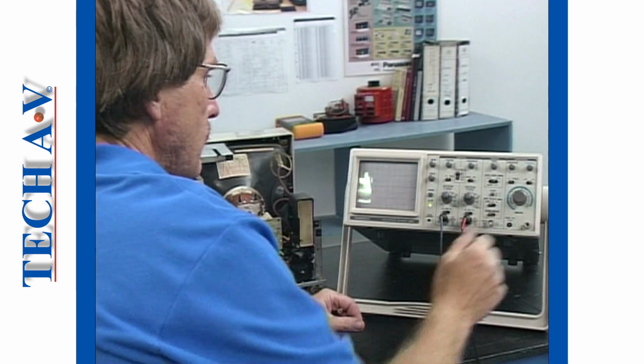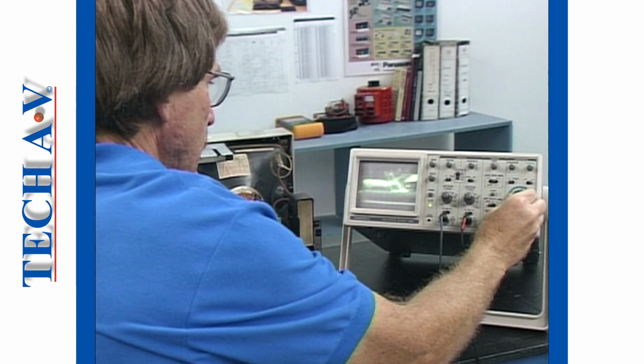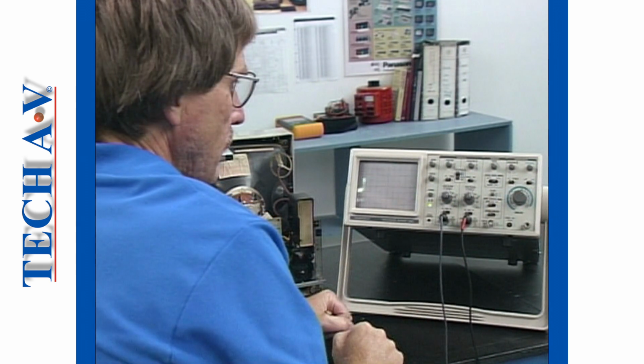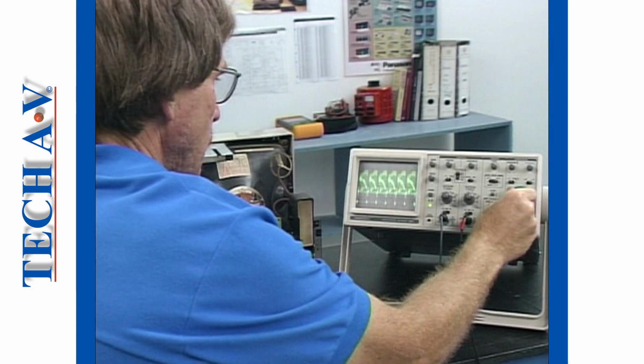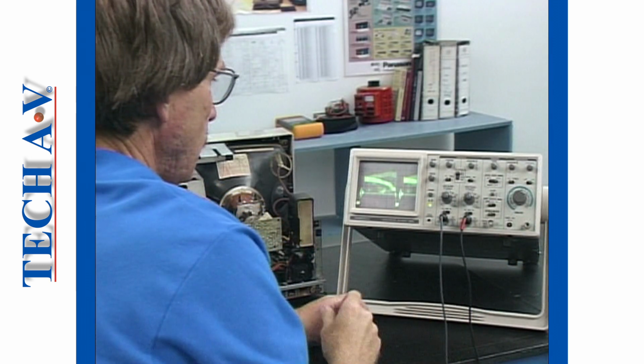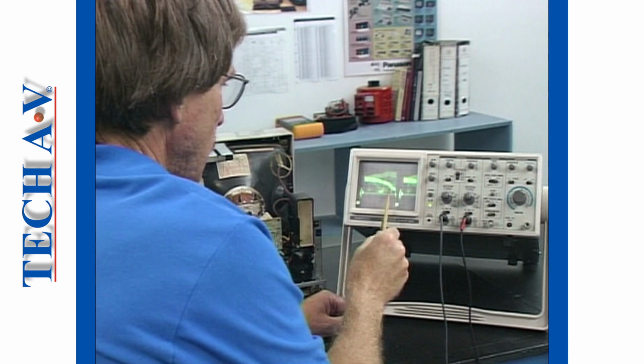To conclude this section, remember that the trace is only stable when the time base is properly synchronized to the incoming signal. During the break, we suggest you practice triggering the scope with a variety of different signals.